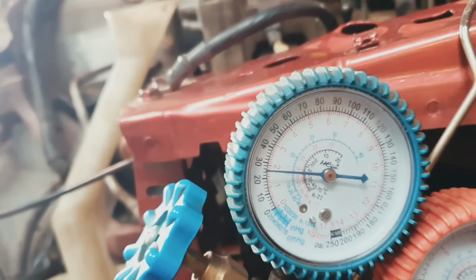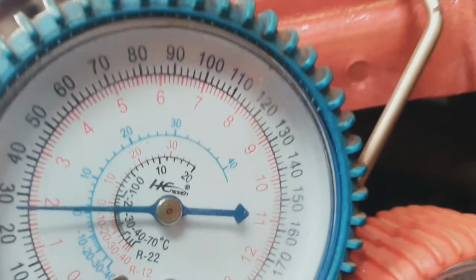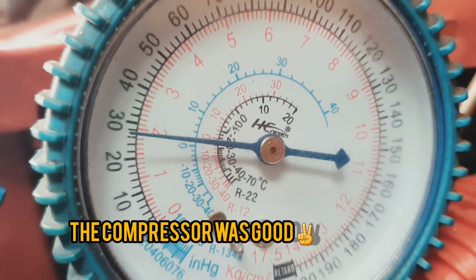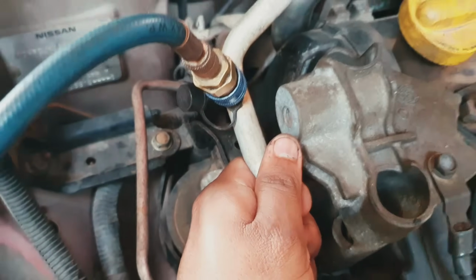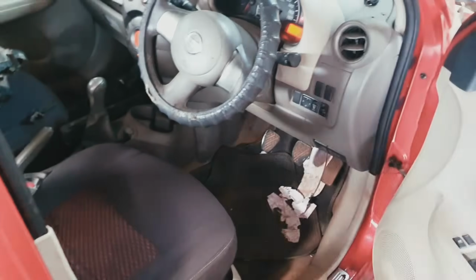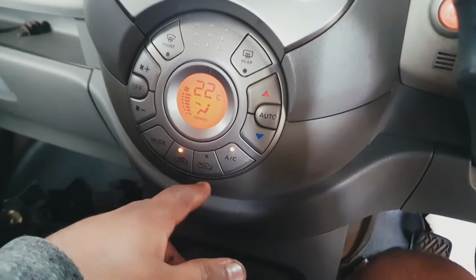Nathan, just accelerate it. Yes. So guys, this is a part where you come to know that the compressor is weak. You see, it is around 30. The pipe is not cooling. Pipe is not cold at all. And I should check inside. Come on. Blower is not working. No, now it's good. So now you see inside, AC is on, everything is on.